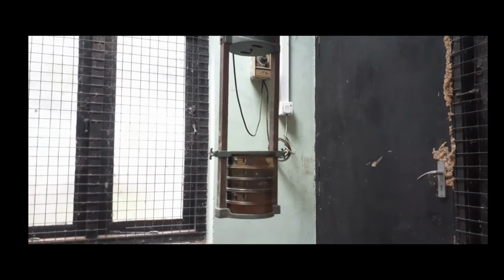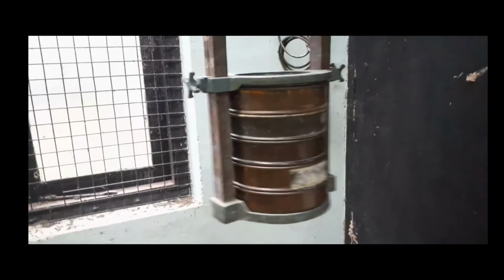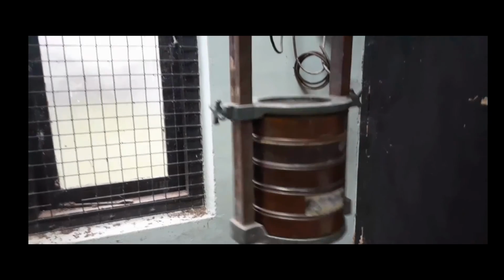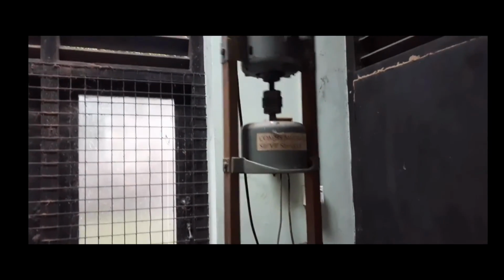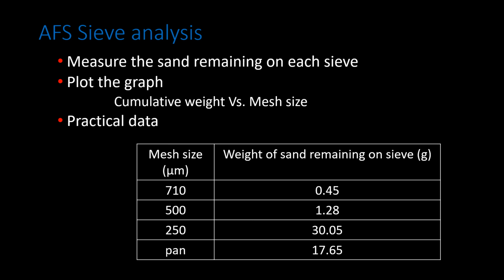After 15 minutes, we measure the weight of sand remaining on each sieve. This table shows the weight of the sand remaining on each sieve. Using this data, you should plot a cumulative weight versus mesh size graph.